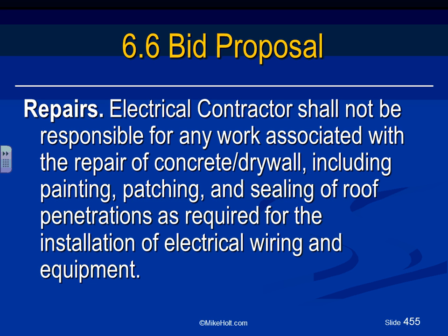They contact the roofers every time you make a hole in a commercial building roof, guys. And with this agreement, they come and patch that hole in the proper way. So in order to maintain the insurance or the reliability of a commercial roof, you almost always have to involve the roofers when you penetrate through the roof.